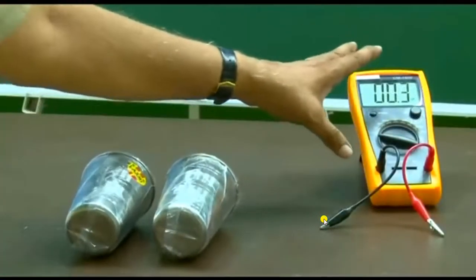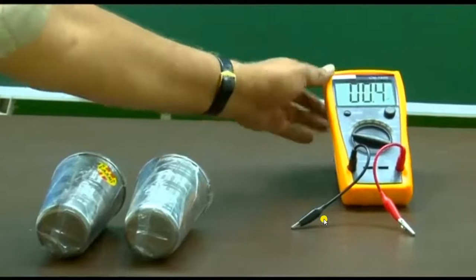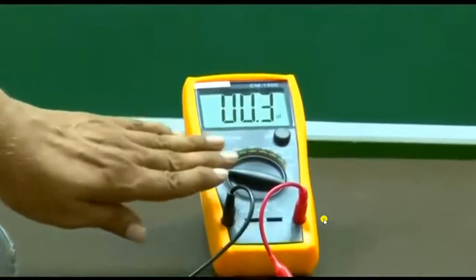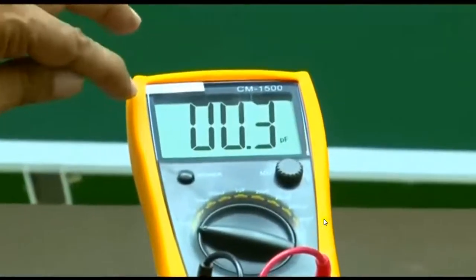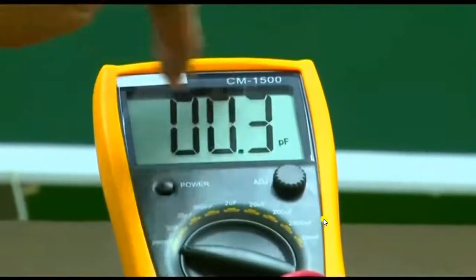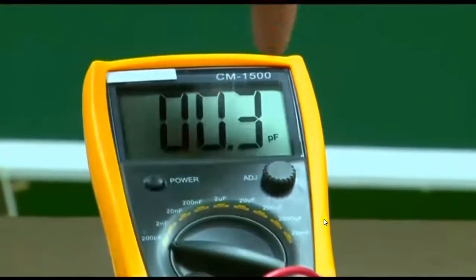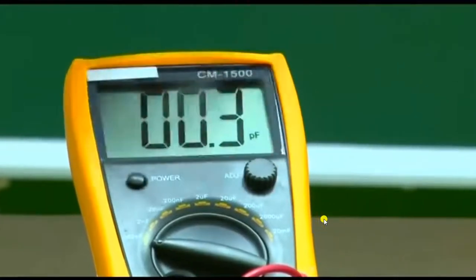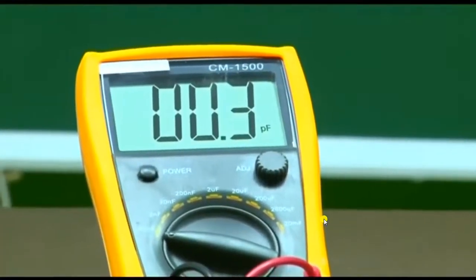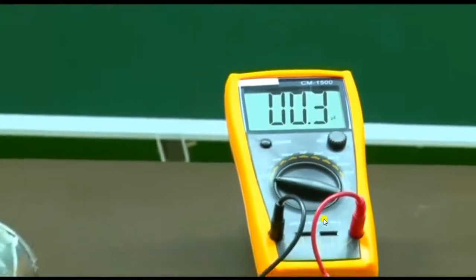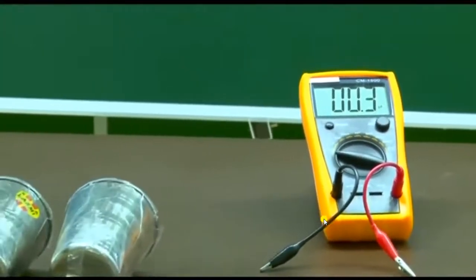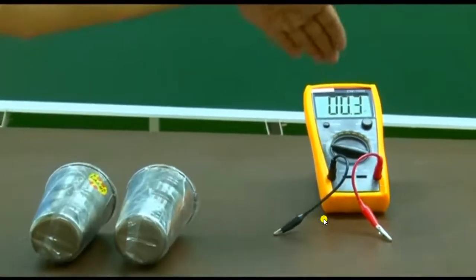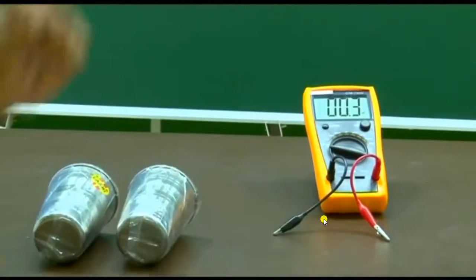First, let me show you the meter. This is the capacitance meter, and we have set all those values, range, etc. And the display here is in picofarads. If you can see on this right side, the small letters, it's written PF. So it's picofarad. Pico means 1/1000 of a nano, 10 to the power minus 12. So those many farads, right? So it will measure in this. This 0.3 is your zero error, you can assume that.